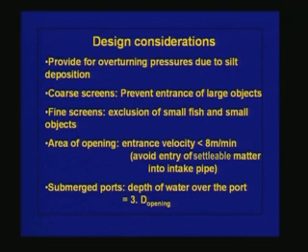And when we have submerged ports, the depth of water over the port should be more than 3 times the diameter of opening. What happens with submerged ports is very similar to what you see in a sink. If there is not enough depth of water above the bottom opening of your kitchen sink, then you will see an air core forming, and air can get sucked into the inlet pipe.